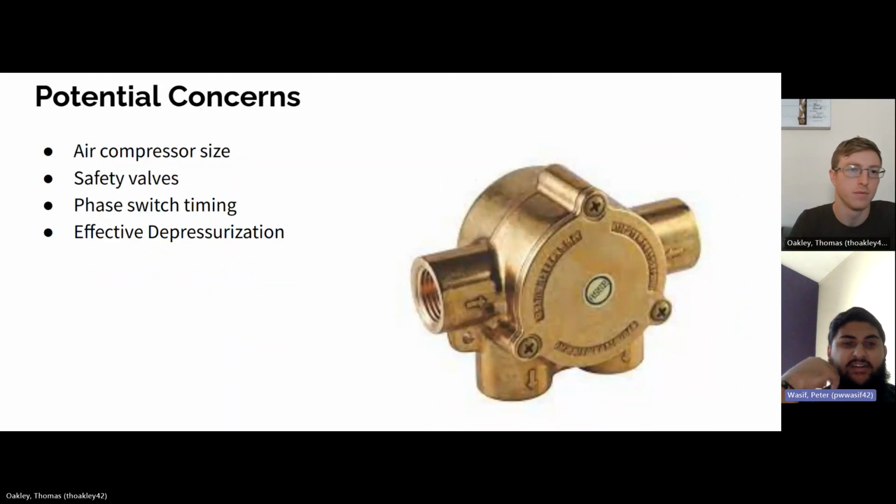With potential concerns, we have air compressor size, which you must take into account, safety valves, making sure that those are working properly, phase switch timing, and effective depressurization. If you can't effectively pressurize, you will not get a good purity of the nitrogen gas.